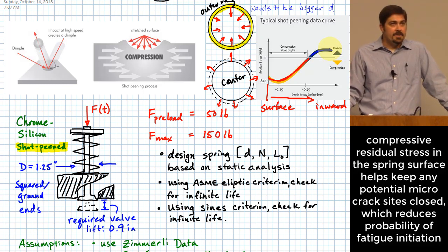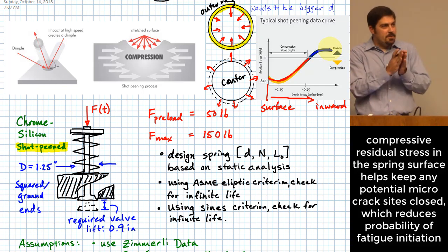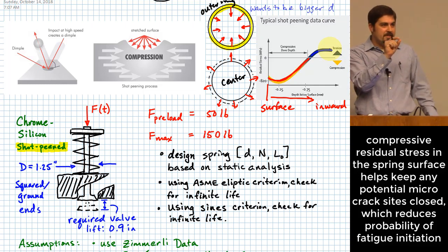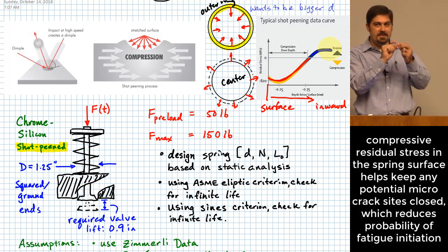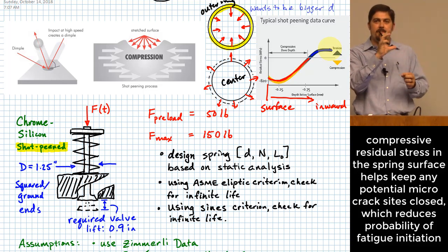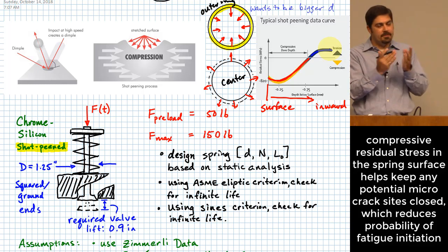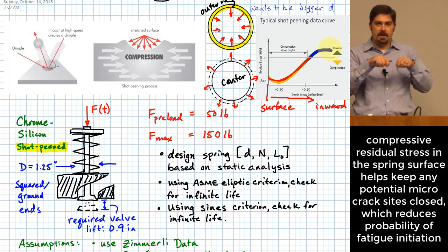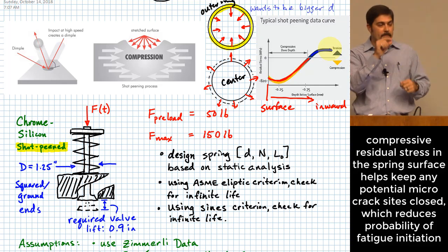Fatigue, as best we understand it, is caused by little cracks that exist in the material, little imperfections that, as you begin to load and unload and load and unload, are stretched apart a little bit, and there's probably a little bit more failure that happens at the tip of these little micro cracks each time that you open it up, and each time that you close it again. It's probably a similar kind of process to bending a paper clip till it breaks, but locally right at the tips of each of those cracks, right?